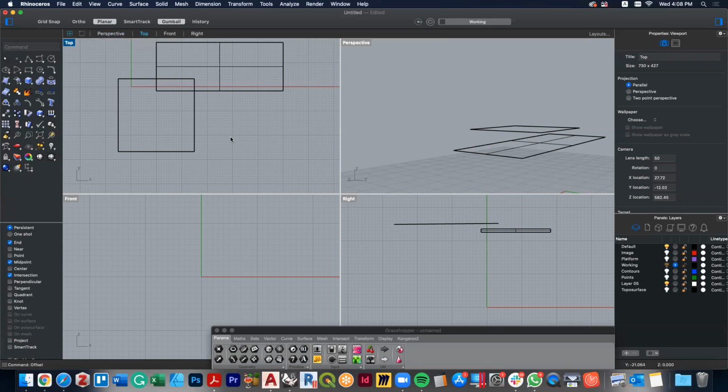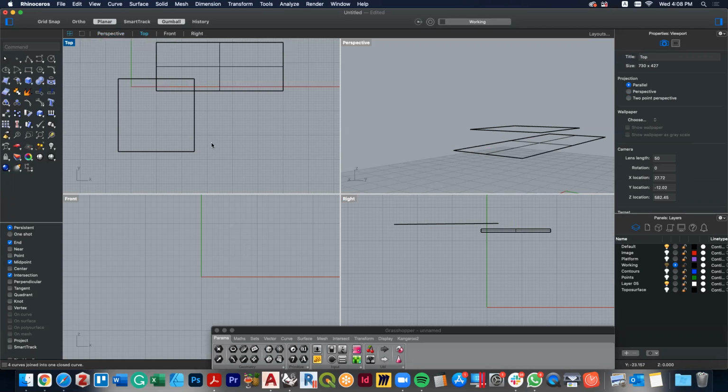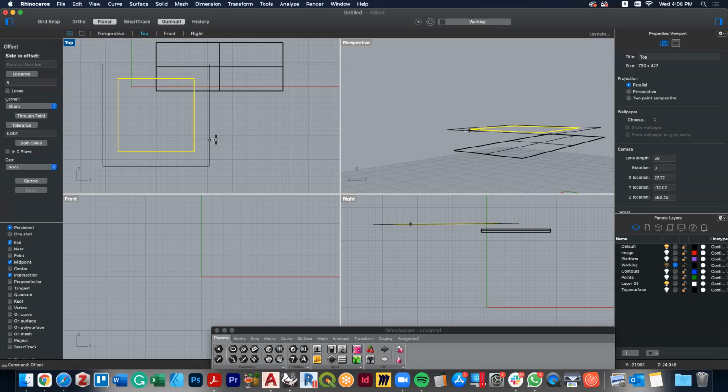Well, first of all, I'm actually going to join it back together again to make one thing. And then I'm going to offset it, maybe by 3 meters. So 3 6s there. If I go 3 meters vertically, it would be 9. And so let's offset it 9 actually.